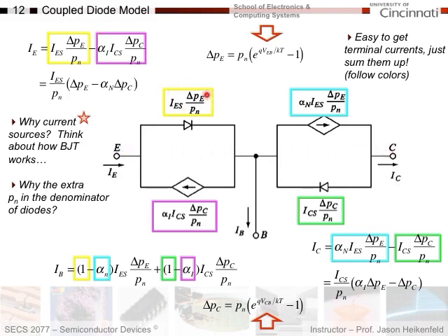And so if I have normal mode and the inverted mode for the emitter, and they're both connected to this node of the circuit, then of course my current here is this, because they're in the same direction, minus this, which is in the opposite direction of how I've labeled my emitter current. Okay? I do the same thing over here. Here's my collector current. I'm labeling it in this direction, and so my normal mode for the collector current, in blue, is shown here. Same positive sign as collector current because they're both in the same direction. And this one is a diode in this direction here, and so this will be current flow in this direction, so it is in the opposite direction. It's got a minus symbol. That would be inverted mode for the collector.